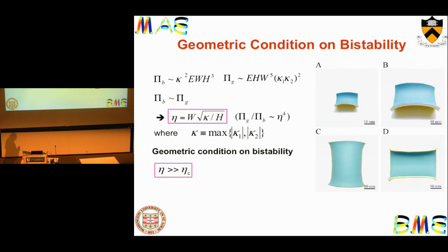And the reason being that the stretching energy over bending energy goes as eta to the 4th. And so when eta exceeds a threshold, meaning when width becomes very large or when it becomes very thin, the stretching energy will be dominating, which is not good because we know nature always likes lowest energy configurations. But it's okay if the system adopts a shape with nearly 0 Gauss curvature.